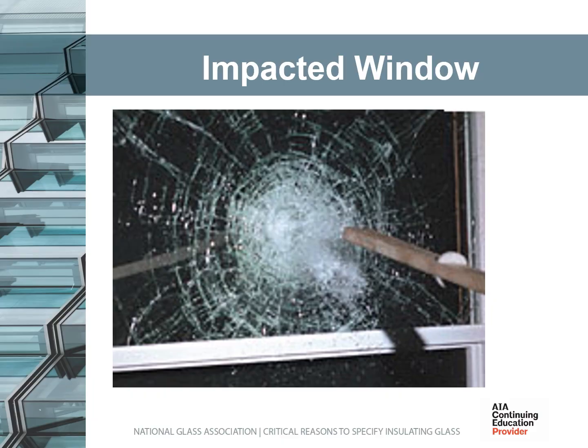For windows, doors, and curtain wall systems designed for use in hurricane or high-velocity wind zones, third-party testing is done to simulate windborne debris striking a window during a hurricane. This is a two-part test. Part 1. In a controlled laboratory setting, a 2x4 projectile or 2-gram steel shot balls, depending on required protection level, are fired at predetermined locations on the window and seeing if there is any penetration.